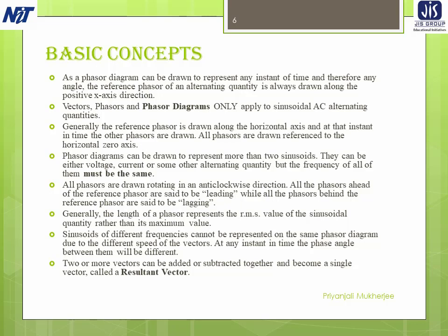They can be either voltage or current or some other alternating quantity, but the frequency of all of them must be the same. All the phasors are drawn rotating in the anti-clockwise direction. All the phasors ahead of the reference phasor are said to be leading, while all the phasors behind the reference phasor are said to be lagging.